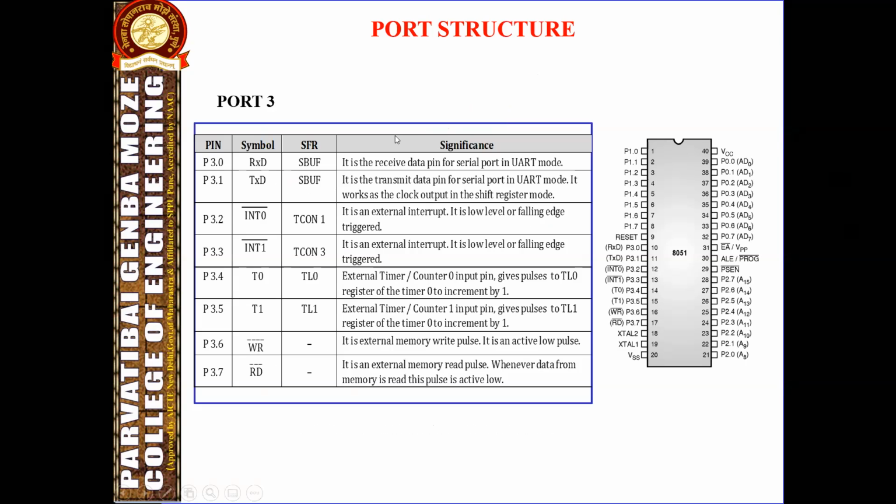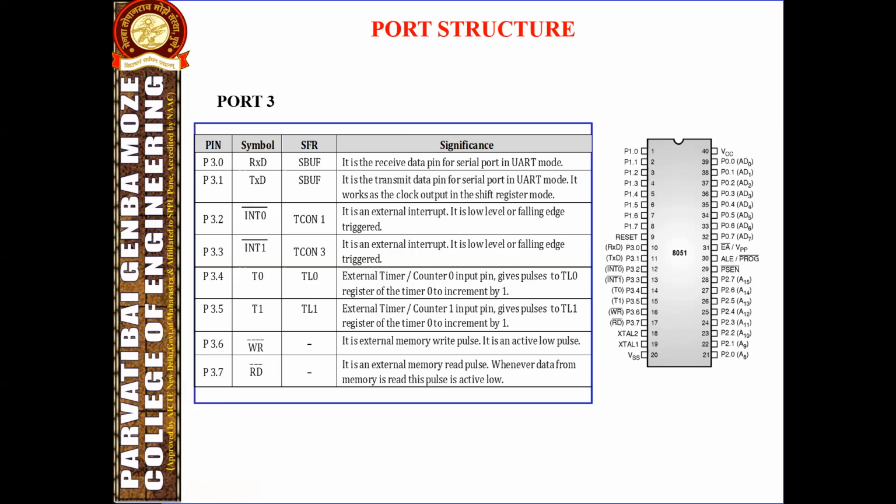This is port 3. Here in port 3, all the pins are multifunctional pins. It can be used as simple input output ports, or the port 3 pins have special functions. The address is B0H and it is a bit addressable port. The pin P3.0 is